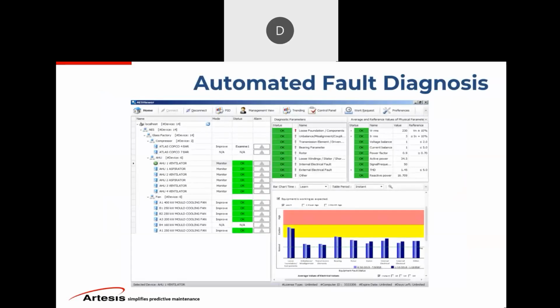And then this is the real powerful page. This is the on-premise software. We can now start drilling down into what those faults are when it does show you red in the overview page. So we look at the bar graphs here. We have a few in caution. The light blue bar graph on the left is what it saw during that learn period that Tumay just explained. We get that initial learn period. We don't really have a baseline because that baseline is already known for that particular motor in our model base of millions of motor signatures, and that's that green line that we have here.